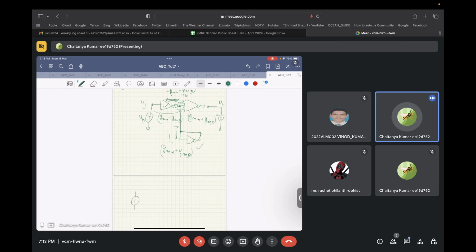Now what we have over here is VB over here, this thing over here, and a VB over here. So now this voltage is biased at VB. The gain from here to here is minus 1. Now, if this is VB plus some small signal voltage VI, what will be the incremental voltage at this node? It will be minus Vi.